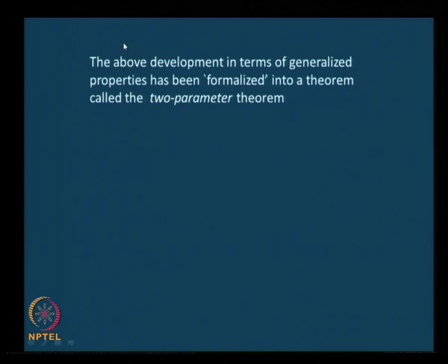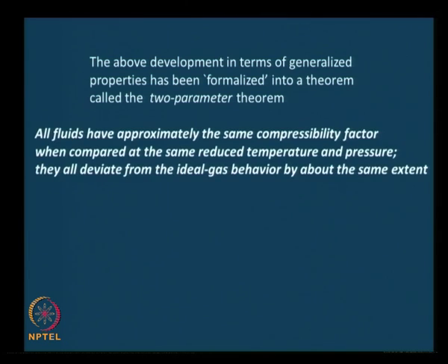Whatever we have said so far in the generalized equations of state has actually been formalized into a theorem called the Two-Parameter Theorem, which essentially states that all fluids have approximately the same compressibility factor when compared at the same reduced temperature and reduced pressure, or in other words, they all deviate from the ideal gas behavior by about the same extent.